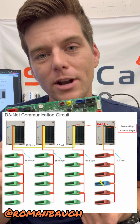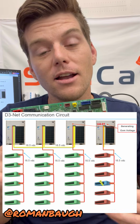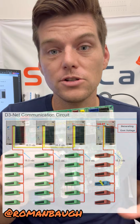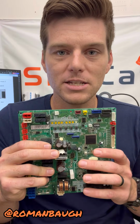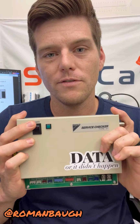That means remove the F1, F2 out wires when you're troubleshooting U4s on a system to rule out that it's not another system somewhere else in the communication network or your centralized controller that's causing the network to crash. Isolate the COM wires and troubleshoot the F1, F2 in wires to the indoor units or the BS boxes. And remember that just because there's 25 outdoor units on the building, you can't connect your one service checker to the system and see all of those inside.